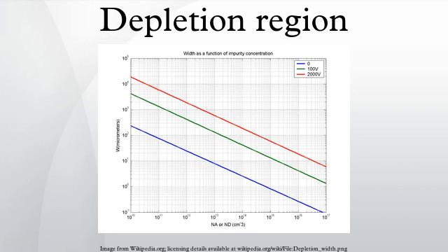Depletion width in MOS capacitor: as in P-N junctions, the governing principle here is charge neutrality. Let us assume a P-type substrate. If positive charge Q is placed on the gate, then holes are depleted to a depth W exposing sufficient negative acceptors to exactly balance the gate charge. Supposing the dopant density to be acceptors per unit volume, then charge neutrality requires the depletion width W to satisfy